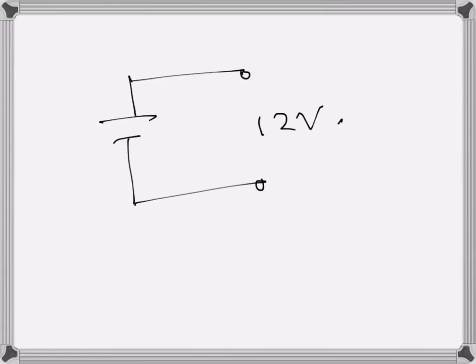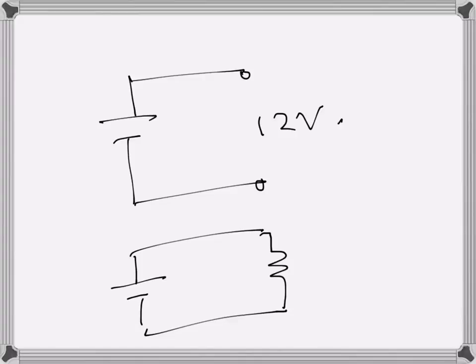So basically, let's say this is the battery. I will draw the battery like this, maybe just the symbol. When it's open circuit, the voltage here is 12 volts, but when it's connected to a 4 ohms resistance here, then the voltage drop here is 10.8 volts.